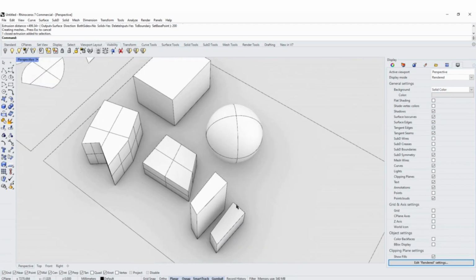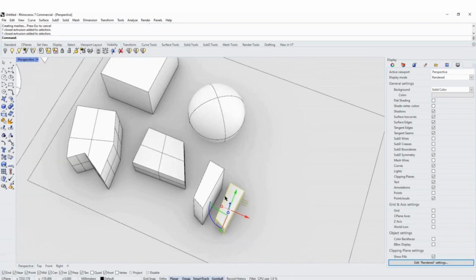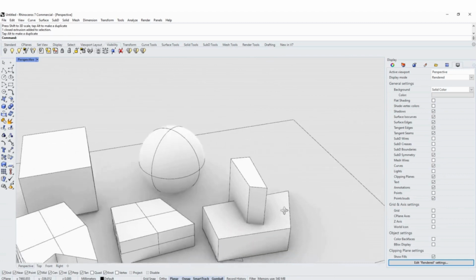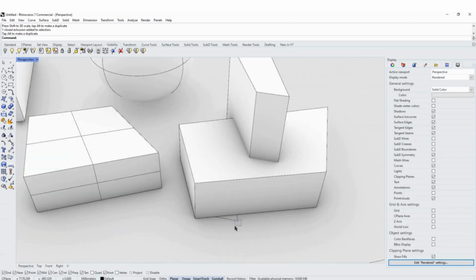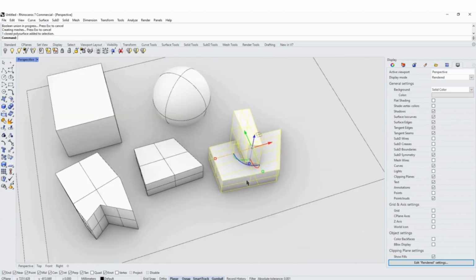But then there are different things that we can do with the solids. So let's say that we want to make this one much bigger. Take this one right in the center of it. Oh, the input curve was still active here, so let's take it and delete it. And let's say I want to connect these two, 1 and 2, into one solid instead of two. This is called Boolean union. So this is right over here, and with the left click, it does the Boolean union, and this is now one item.